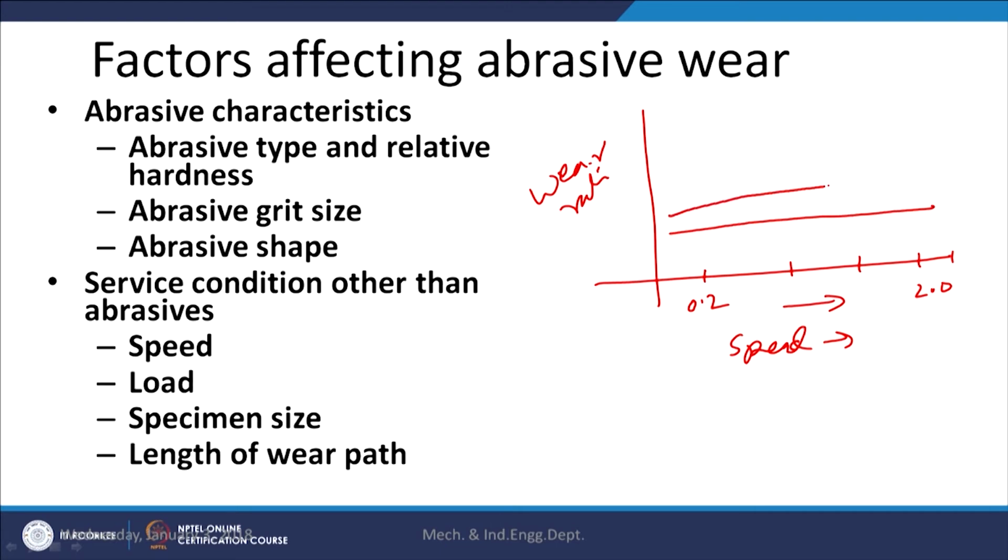So, this slope is very small, which suggests that there is no major change in the abrasive wear rate with the change of the speed at which the abrasive action is taking place. Whatever minor increase in the abrasive wear rate is occurring is attributed to the increase in temperature due to the localization of the heat generated, which leads to a minor reduction in the hardness.